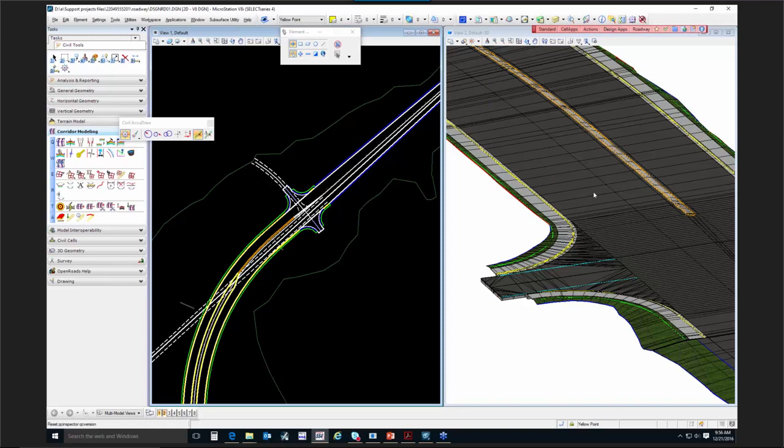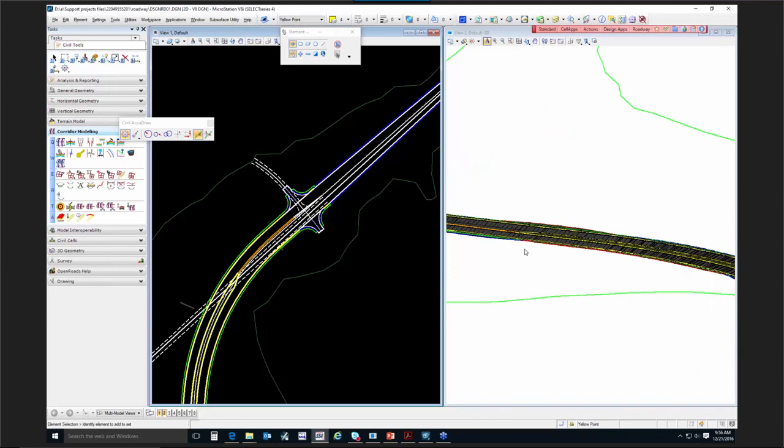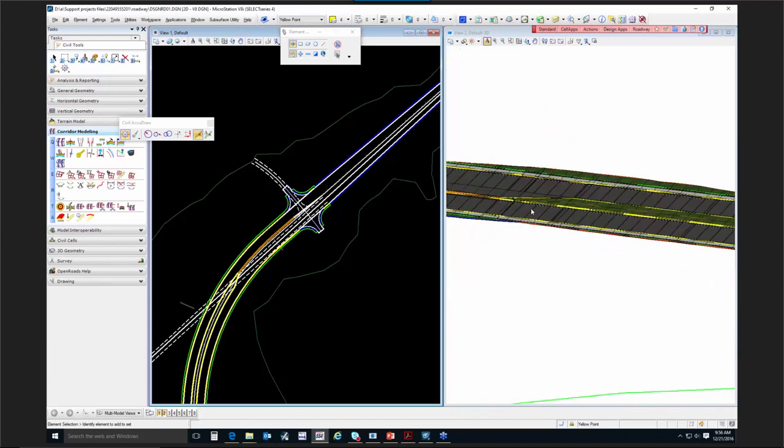It's when you start going rogue with making your own templates and not using the same features that we're using for things like sidewalks and pavements and feature names for points, that's where you're going to end up failing your QC on your model. But we're already checking the default 3D for the models that we want you to display things on. And it's essentially, if it's a shape, it should be a PX. If it's a line, it should be a PM level. Anything else shouldn't really be in this default 3D.